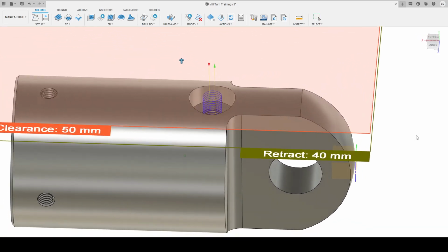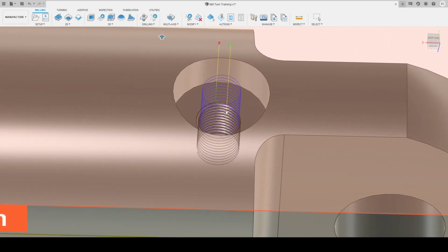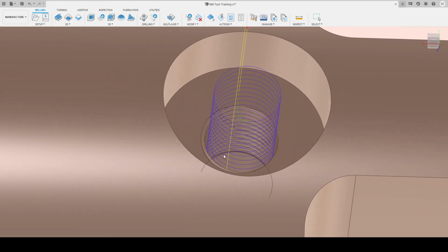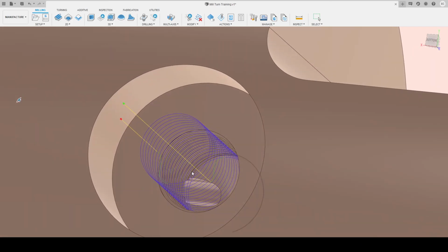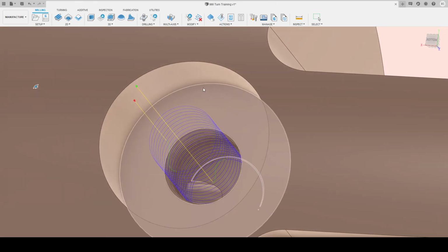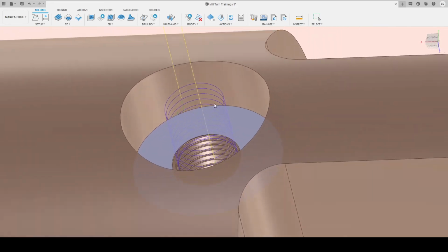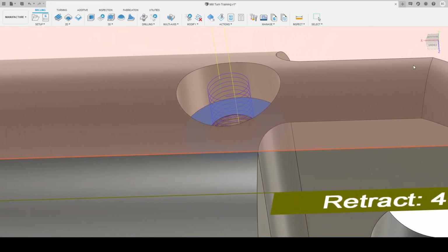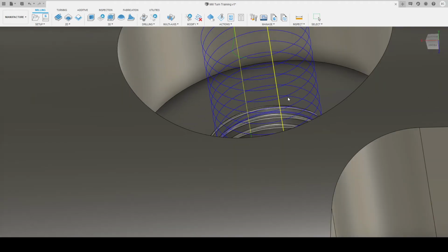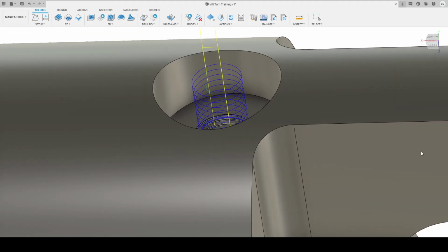And you can change these as well. So if you don't want it to go to the bottom of the hole, you can go selection and select something else. You can select down here and it'll actually bore right down to the bottom. But for today, all we want to do is bore down to this face. So that's fine. Again, we'll throw a cleanup pass on it. So under passes, we'll go finishing passes and just add 0.1. So it actually leaves you a lot nicer finish. So we'll go OK.